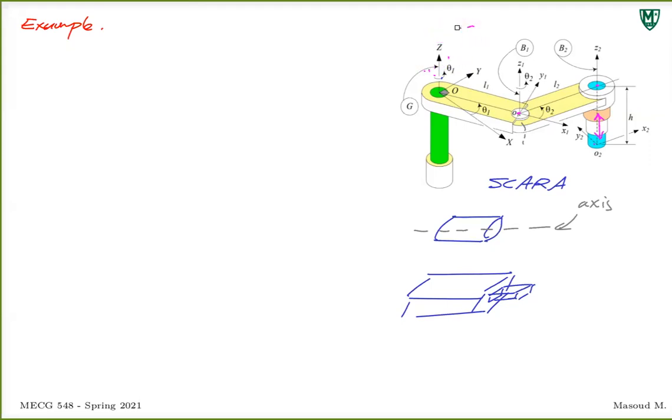Well, prismatic joints are really pretty straightforward, I think. It's a linear translation, or a linear motion. So we can get a sense of positive and negative depending on which axis you are. In this case, let's look at B2, right? This coordinate frame, B2. In this case, since Z2, I'm looking at this right here, and this is a prismatic joint going up and down. It can elongate and it can retract. In this case, it's kind of obvious that when you're going upward, it's positive, you're going in the positive direction of Z2. When you're going downward, you can think about it as negative.